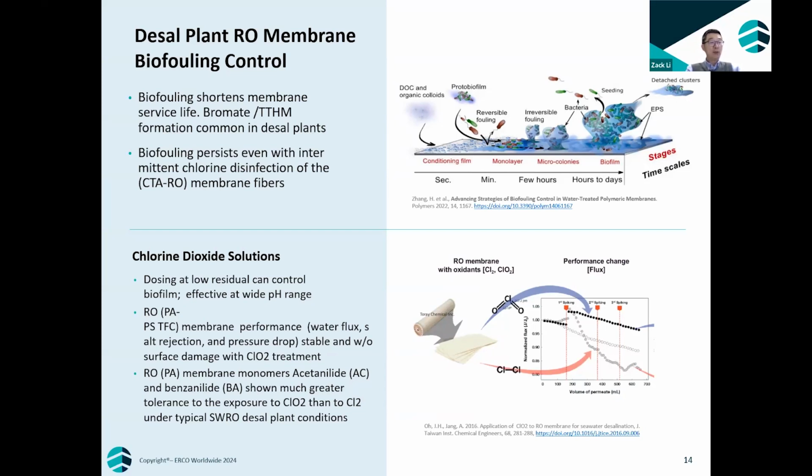Also, oftentimes, chlorination of RO membrane has been reported to be either ineffective in controlling biofouling or sometimes even make it worse, because of the increased content of assimilable organic carbon produced by chlorination. Chlorine dioxide, on the other hand, can be a very effective alternative biocide to chlorination, because pre-treatment with chlorine dioxide instead of chlorine can better control biofouling and eliminate bromate and bromoform DBP formation.